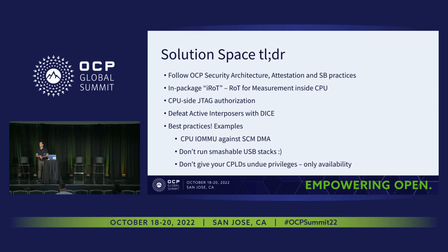Yeah. Thank you for the question. Thank you for explicitly noting JTAG authorization. It's an interesting topic to me as well. Obviously, authorization means by default there is no access to JTAG. Now, if the authorization is done via software, not by the hardware, that could lead to a situation where, for failure analysis, we want JTAG to be unlocked, and yet software may not be loading because of the failure analysis scenario. Have you had thoughts on this scenario?